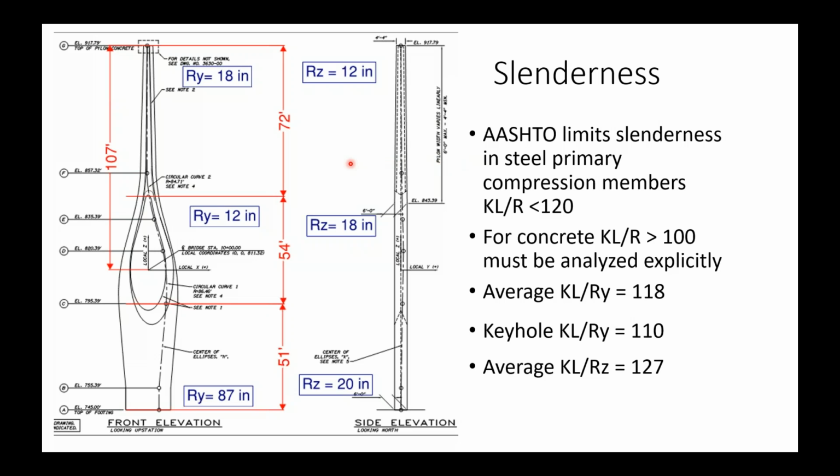And again, in ASCE, there's not a whole lot of guidance given about how close to the buckling load you can get without exceeding the code. They just suggest that you look at it, without a lot of guidance. And for my own personal evaluation on an element like this, I like to have a very comfortable margin of safety against buckling.